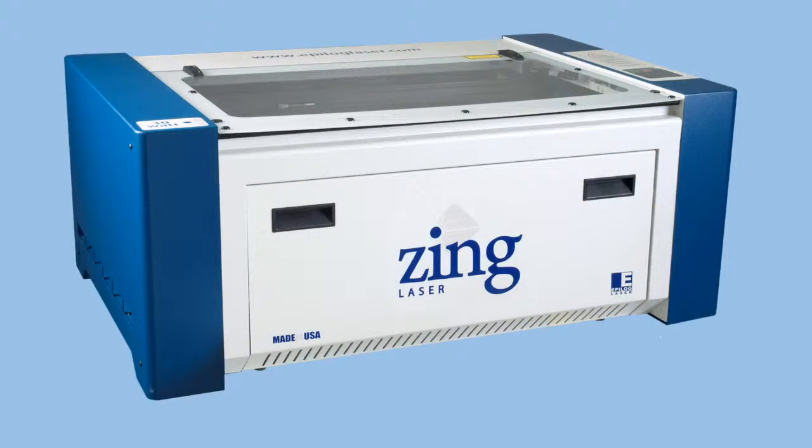To give an example, this is a picture of our laser cutter. It is an Epilog Zing laser cutter. It has a working area of 1 foot by 2 feet, so you can engrave anything that big. It can engrave on objects up to 7 inches thick. So if you had a box or something, as long as it's less than 7 inches, we can fit it in the machine. And it can cut through certain materials up to about an eighth to a quarter of an inch, depending on the material type.